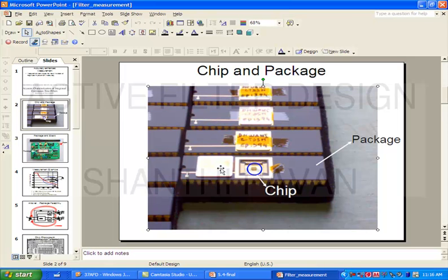It can't be wireless, right? So there has to be a wire which connects the die to the package. This is usually a gold wire, okay, and this whole process is called wire bonding. In a semiconductor line there will be an automatic machine, a robot type thing which has memorized the locations of the pads and the corresponding points in the package, and it rapidly goes from pad to package, pad to package, pad to package, cutting off the wire after the bond is made, and so on. All this happens very, very quickly.